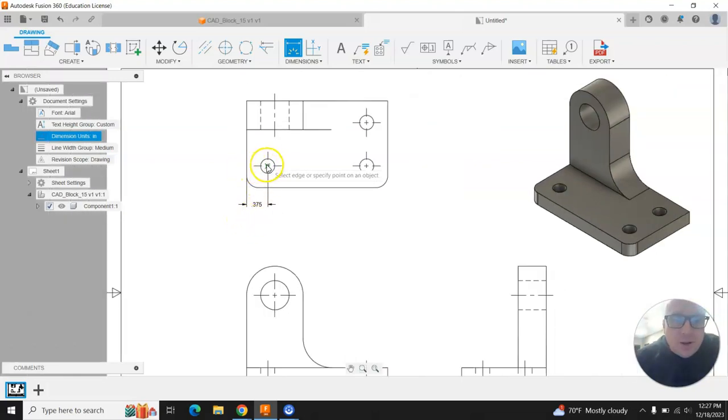So again, moving from left to right across the object, the next thing I run into is the center line for the hole that goes through the object. I'm going to do that one in the front view because again it shows the hole detail in that view. The next thing I run into is this edge right here. That's the overall edge of the object, so I'm going to dimension this arc right here as a radius. I'll click to place that dimension right there, and that radius gives us the dimension. That's from the center point to here, so the overall diameter of that is 1 inch.